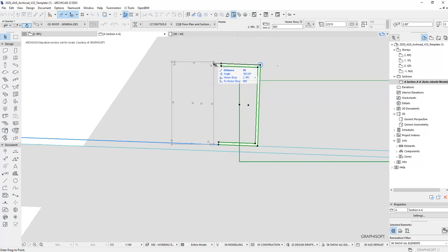And that guideline there is basically referring to the 2-degree. Okay, so again, to do this, I need to make sure that I hold Shift. Okay, hold Shift, and it will lock this down by using the 2-degree. Okay, I'm just gonna maybe stop here.